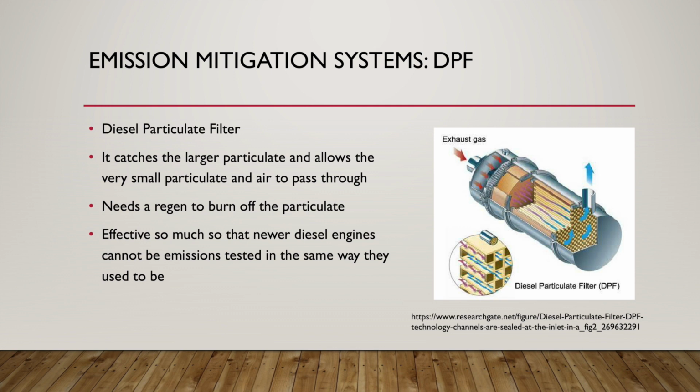Now, what's really interesting about the particulate is that the big, large particulate that we saw in the previous slide, where there's that Peterbilt truck with all the black smoke, falls to the ground. But because we're filtering it so much, we just have tiny particles. These tiny particles stay airborne, because they don't have any mass and don't fall to the ground. So we just breathe them in and they get stuck in our lungs. We don't have any of the big particulate, and yes, we're not polluting as much particulate matter because everything is tiny. But what we are polluting is small enough to get stuck in our lungs.